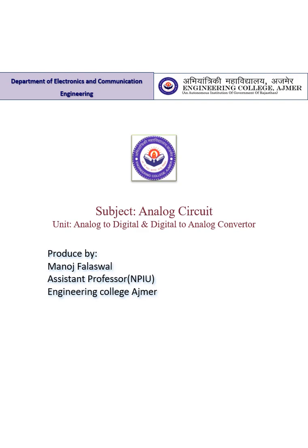In the last lecture, we discussed the successive approximation register type analog to digital converter. In this type of ADC, we have seen that the conversion time is independent of the applied input voltage and is always equal to the number of clock pulses applied, or the number of successive approximation register or ring counter stages we have used.